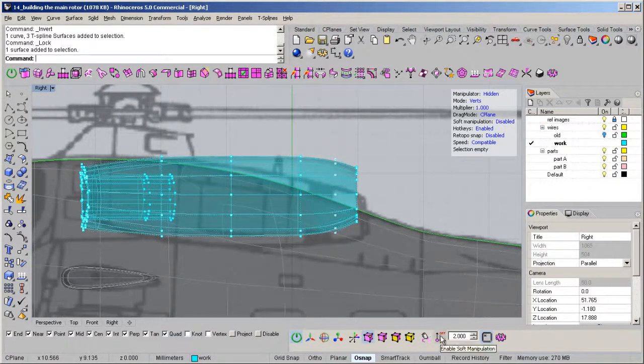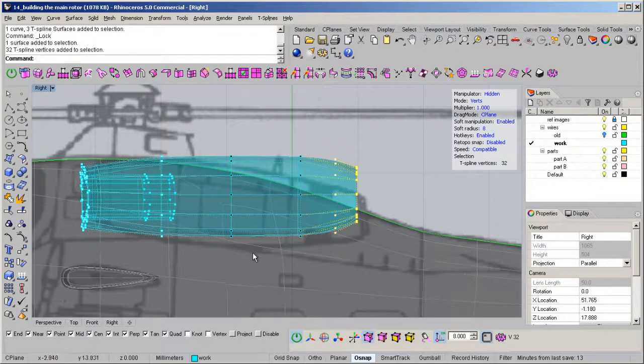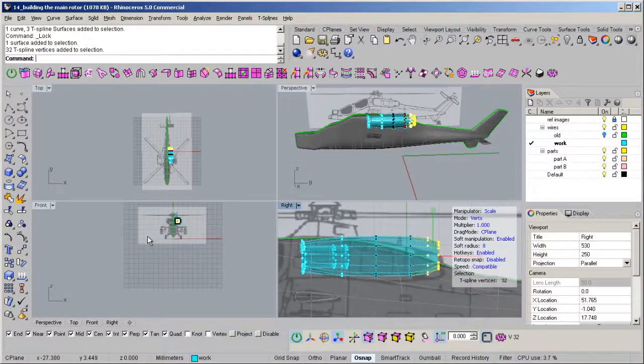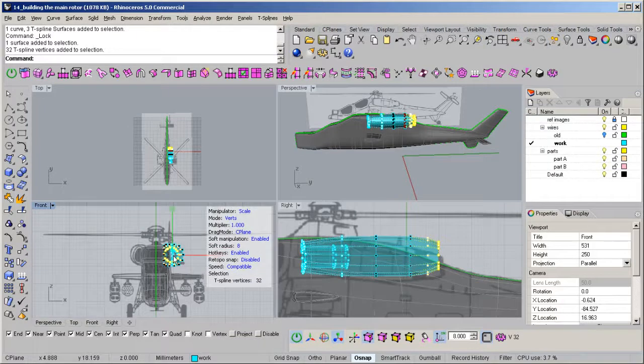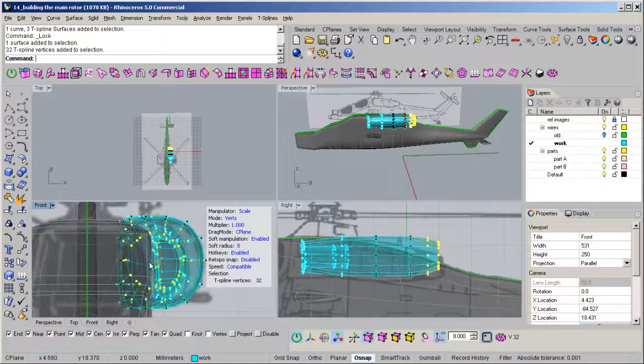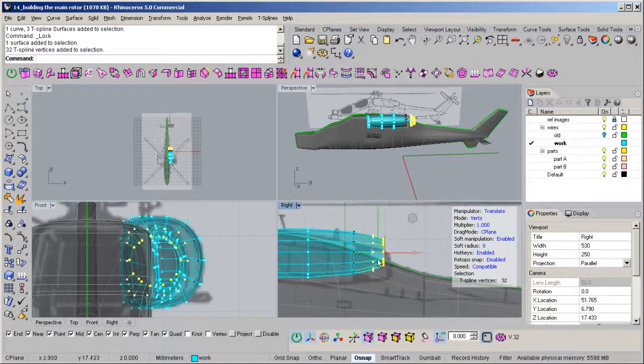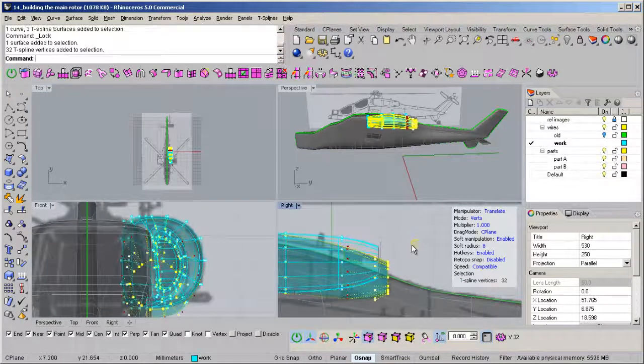You can turn on the soft selection mode again. And let's try changing the number to 8 and see what happens. I'll grab this group of verts here. Notice my falloff is not too strong. And when we go to start with the scale tool, let's switch over to the front view and let's scale it down just a tiny bit. That's good. A tiny bit more. And let's switch back to the move and just drag it down just like this.